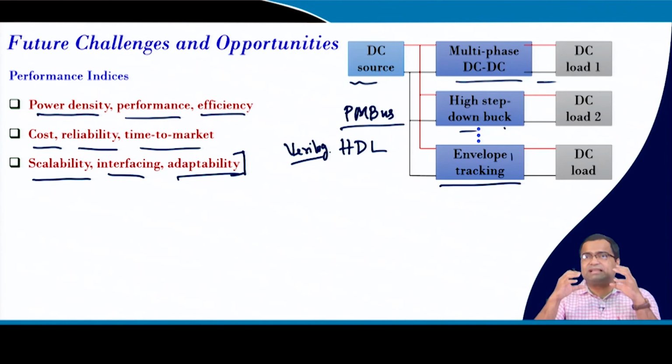So, you can use them to develop your controller, and you can prototype using an FPGA. When these are tested fine, they can be synthesized by any professional tool or software like Cadence or Synopsys, and then you can synthesize the particular digital circuit using the process technology that you are going to use. Okay. So, it should be an adaptive solution.